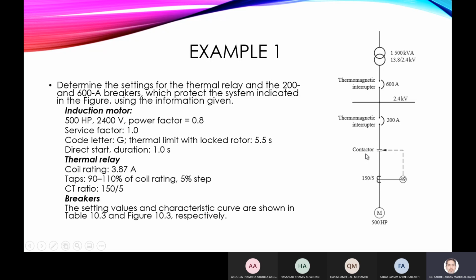So if the rated current of the contactor is, let's say, 100 ampere, they can break up to 1000 ampere safely without damage. If the current is higher than 1000, it will get damaged. So you have 10 times its rated current capability. So if the short circuit current is more than 10 times, and you have a relay that detects this short circuit and gives a command to the contactor, it will get damaged. That's why we rely on a breaker to trip these short circuit currents.